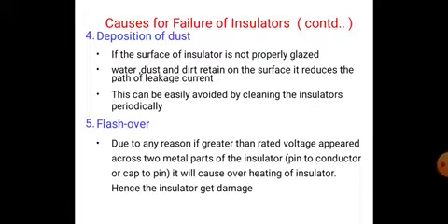Due to atmospheric conditions, the insulator may heat up to a certain temperature, and after that temperature the flashover will occur. When a breakdown due to flashover occurs, the insulator will continue to act in its proper capacity after the event unless fractured by the heat of the arc. Whether the insulator is dry or wet due to rain, the flashover voltage is expressed as dry flashover voltage or wet flashover voltage. Dry flashover voltage is more than the wet flashover voltage.